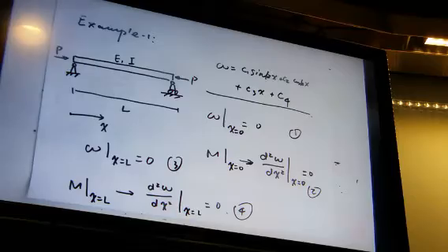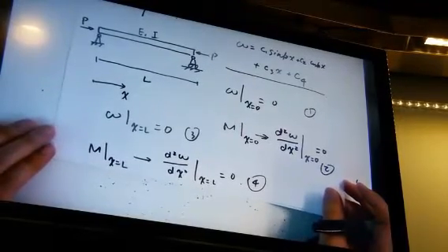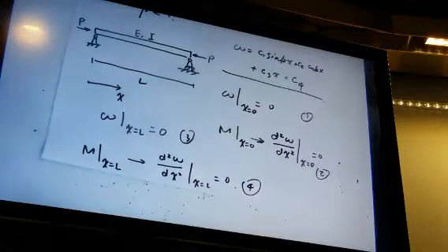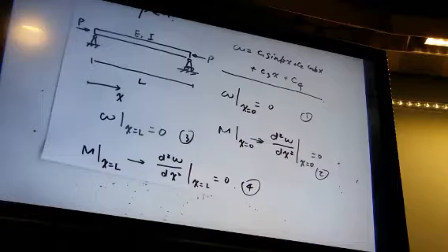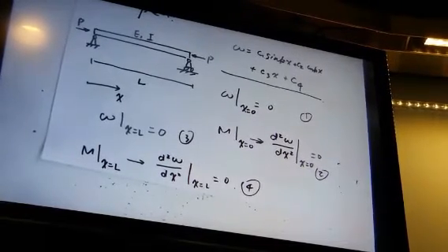I'm going to continue introducing the analytical analysis of buckling of structures. Buckling is a kind of failure mode. When you apply a compressive loading on a structure, sometimes the structure becomes unstable suddenly. And what is that critical compressive loading? This is basically the objective of buckling analysis of structures. We're trying to figure out this key: what is the critical compressive loading to make this column unstable?